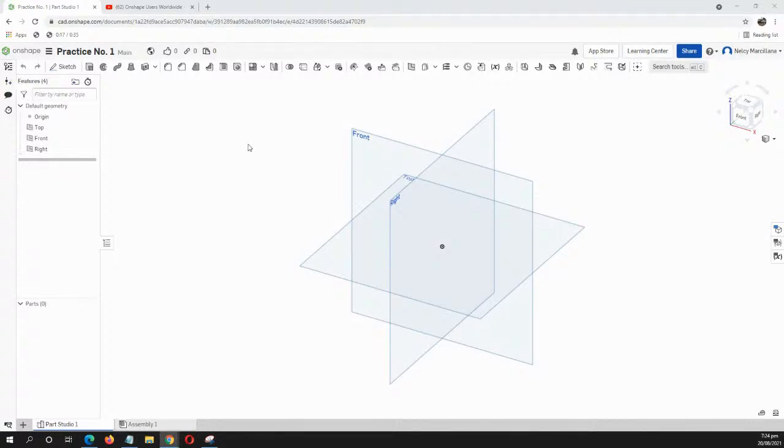Okay, so our sketch is in millimeters. By default, Onshape is in inches. So let's head over to the Document menu, selecting Workspace Units. We have different units of measurement. For this one, let's use millimeter. Leave all the defaults and click the green check mark.